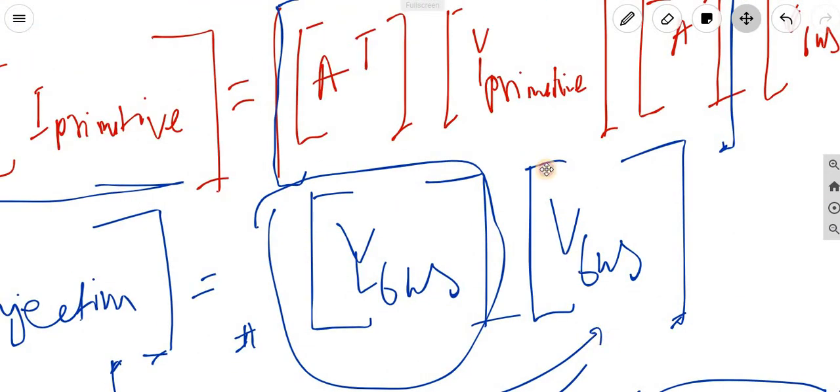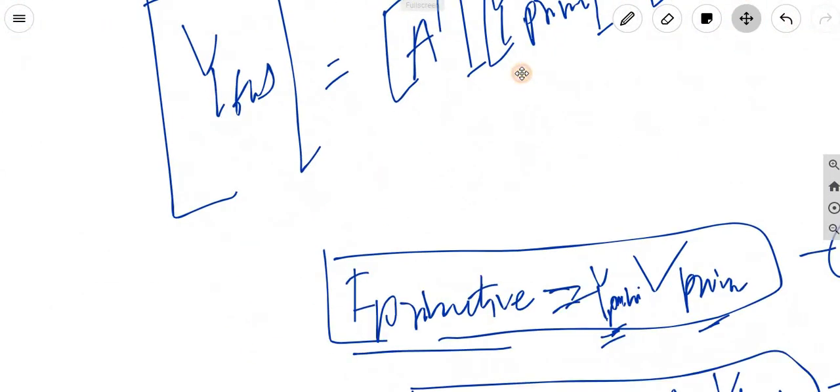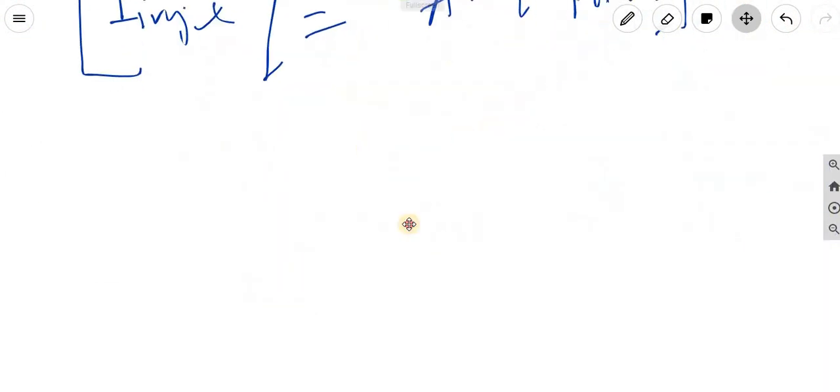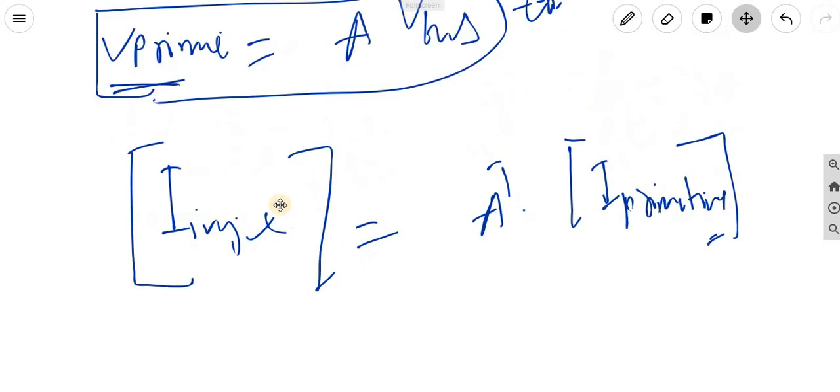So with this I will give one problem also, so try to solve this in this way. Okay, firstly you form the primitive matrix, then you form the incidence matrix, or the branch voltage related to the bus voltage. Okay, so that incidence matrix we form first, and the primitive matrix.